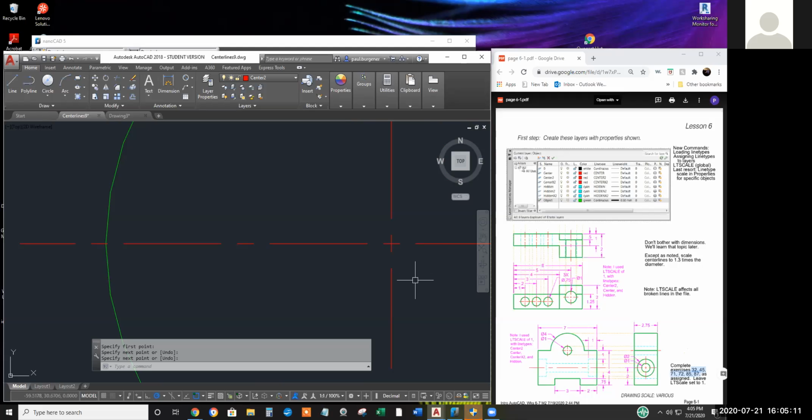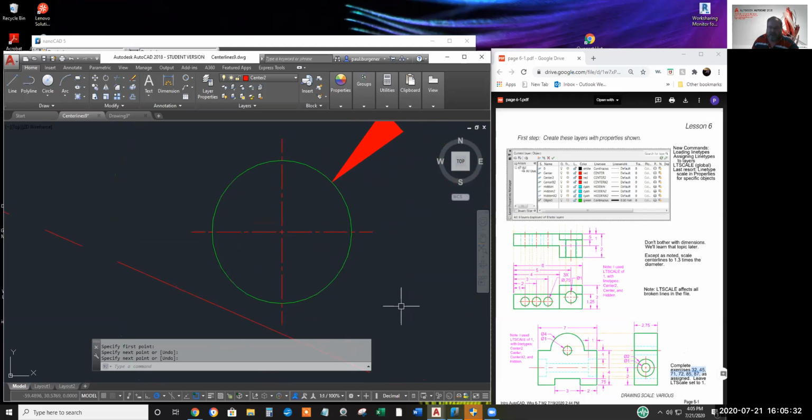So what I ended up doing was I'll go into the paper space, and then through the paper space, I swap over to model space, looking through the paper space, and then change it so that it looks right. Okay, I'm with you. Yeah, it's a trick. Okay, I was thinking maybe you encounter some drawings with that PSLT scale different. I haven't touched that at all yet.